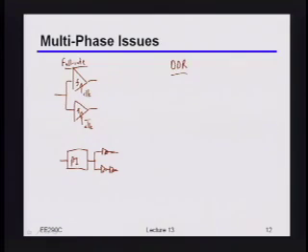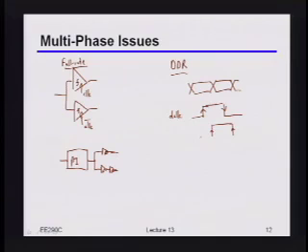Here, if I look at my clock, I'm going to be capturing data both on the rising edge of the clock and on the falling edge of the clock. So this would be my data clock. Now remember, you still also have to do timing recovery, right? So that means I now need another clock that is 90-degree phase shifted with respect to the first clock. Okay?